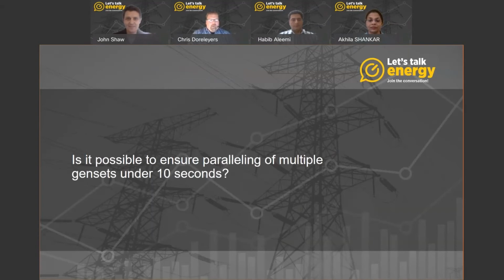Sure, John. Controlled excitation paralleling, or CEP, is a generator synchronizing control scheme that allows the system to start with all the generator breakers closed and then simultaneously control each of the generator's field excitation until the desired generator output voltage and frequency is obtained within a 10-second period.